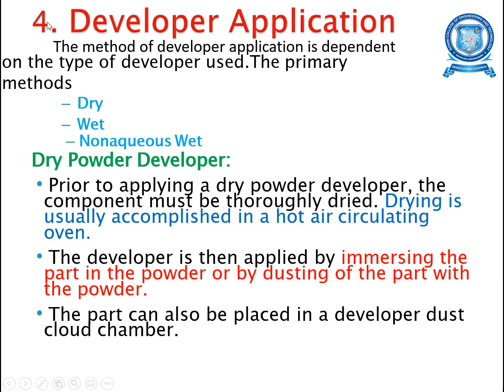And the fourth step in liquid penetrant testing is the developer application. Based on the type of developer, the primary methods involve dry, wet, and non-aqueous wet.